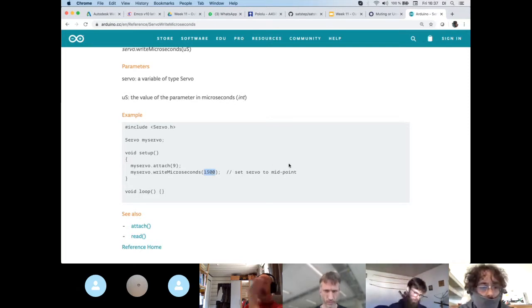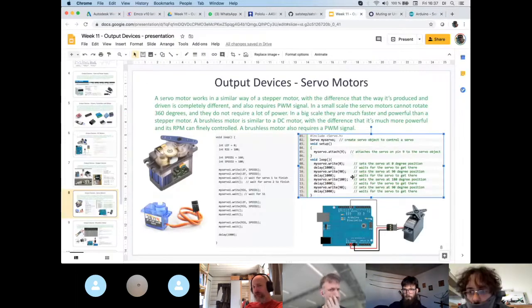William: So my two questions were, with the servo motor, in the example code you give it an angle to get to, and then you wait a second. But that's a guess. You're looking at how long it's going to take for the machine to get to that particular angle. And obviously, if it's a smaller angle, it'll happen more quickly than a second. If I say write 0 and then write 10, I don't need to wait a whole second to go that far.